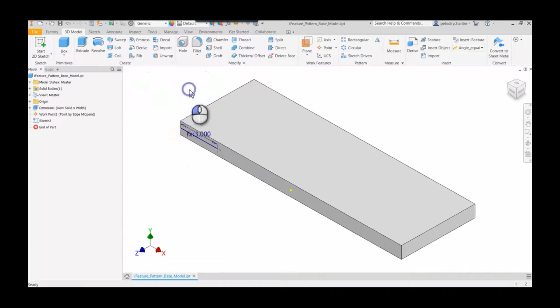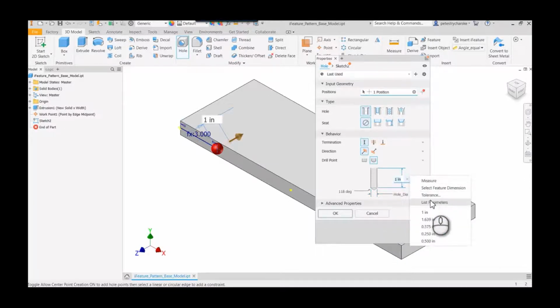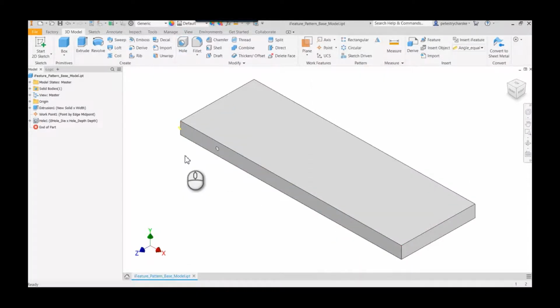and then we can apply the hole. I'm using a very generic hole, with the distance option through the thing. We can of course grab the parameters. That way later on, if we wanted to add controls, we could do that. Where's the depth? There we go, there's the depth. Grab that, and that's going to be the hole depth. So again, pretty straightforward deal there. Hit OK, and there's the hole.